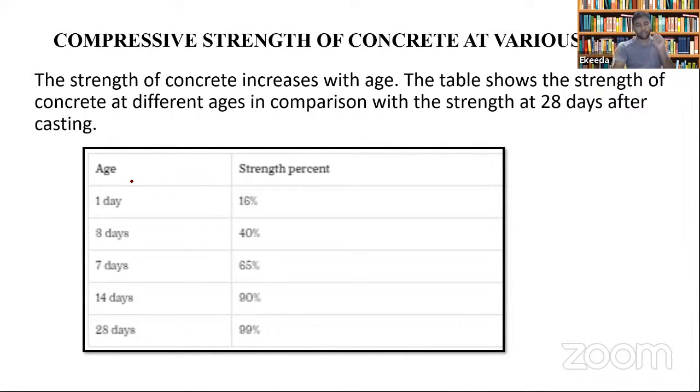Now one question that is always asked by students is, sir, in one day how much percent of strength is gained by the concrete? That is a very common question by every student, that in one day or in 8 days or in 7 days or in 3 days or in 14 days, how much percent of strength is gained by the concrete? So I had prepared a table for you that in one day concrete attains 16% of the ultimate strength.